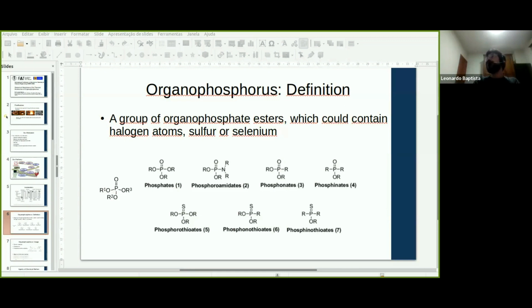So we need to incinerate at temperatures higher than 1000 Kelvin to destroy the organophosphorus compounds completely. Thermal degradation, incineration, is a good method to remove and destroy organophosphorus compounds completely, if we take some care during the process of incineration.